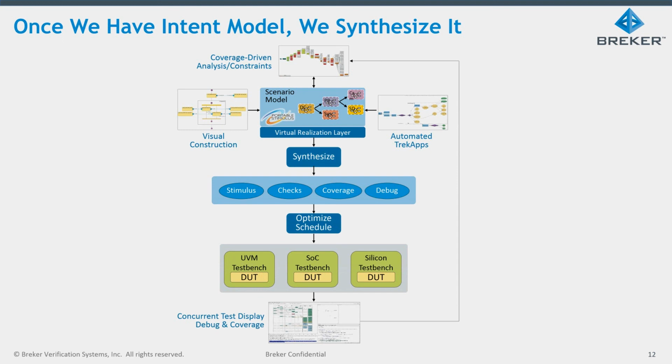That's right. The schedules get wider, the recursion gets deeper, and also there's another aspect that I haven't punched over here in this presentation. At UVM, we're typically running transactions driving into some kind of VIP kind of thing, but most of these things are software driven, right? So as we get up into bigger portions of the chip, those tests become more software driven, and instead of driving UVM VIP, we're generating C code that's actually running on some kind of embedded processor. Okay. This ability to switch it is kind of a big deal. Yes, I can see that.